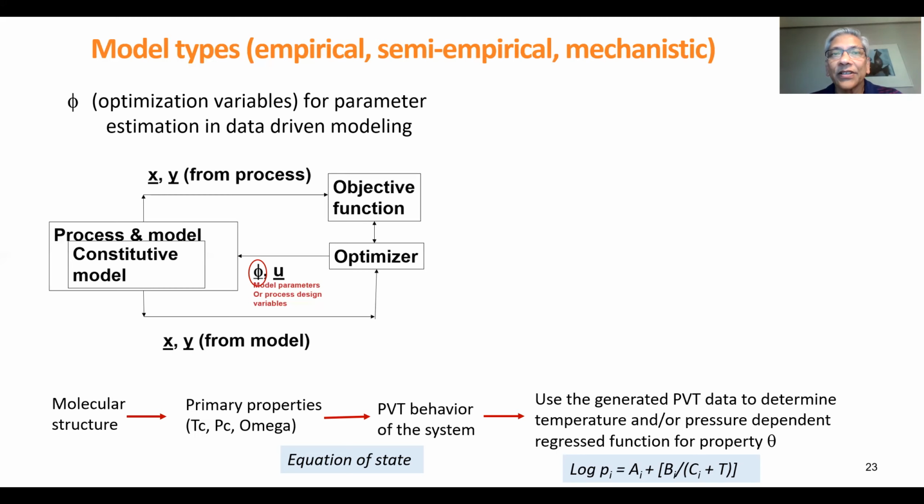But to calculate this, we need the interaction parameters. So we have parameters that need to be fitted with measured data of pressure, volume, and or temperature. And in order to do this, in addition to the PVT relationship, we also need the vapor pressure.